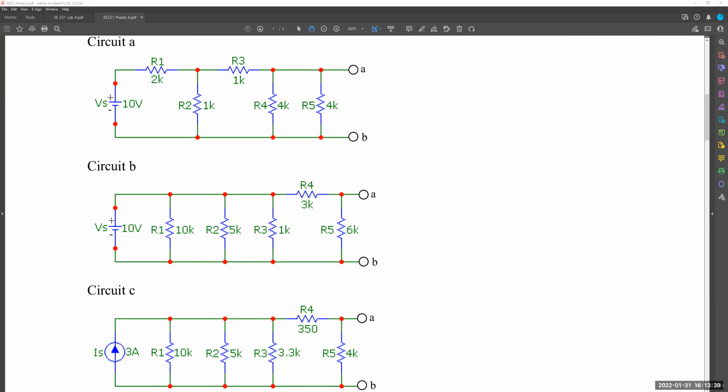Okay, so this technique pretty much works with any circuit. You simply have to take it step by step. And again, you might have to redraw the circuit 3 or 4 times, but eventually you would get the answer. Now, again, this technique does not guarantee that you will get one single resistance, because all circuits are not reducible. But the goal is to draw all the resistors vertically, so at least it would make a bit more sense.